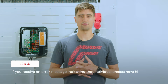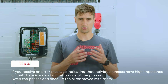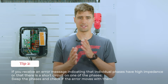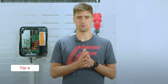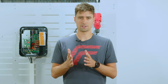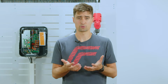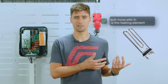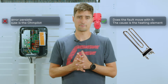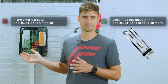And secondly, if you're getting the error message that you have high ohm on one of the phases, then swap phases and see if the error message is moving with you. If you're swapping L1 and L2 and the error message is moving with, then this signalizes that this error is true and actually the heating element is the problem. If the error message is not moving with, then it's likely a failure on the Ohmpilot.